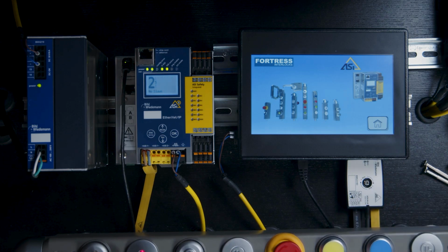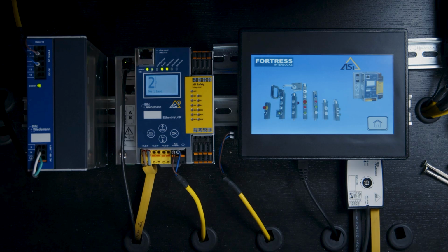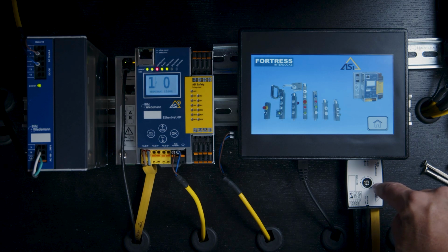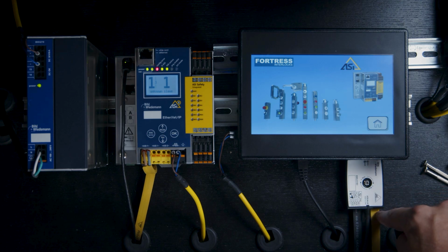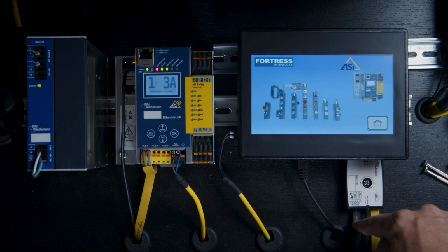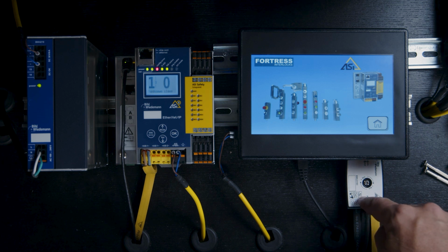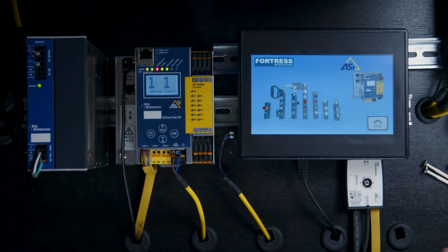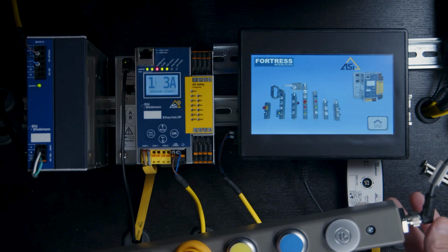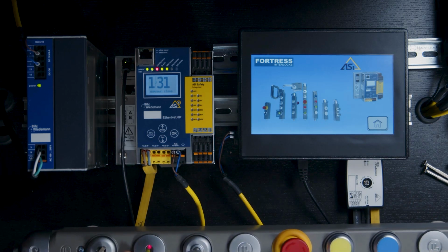So what this device does, let me move the tGard out of the way, is it basically uses the normal ASi vampire technology to create a node vampiring into both the yellow ASi network cable as well as, in this case, the extra flat power cable that some ASi systems use for devices that need more power. And then after clamping on those two particular cables, it provides, coming out this end here, the M12 cable to plug into the bottom of the tGard in this case.